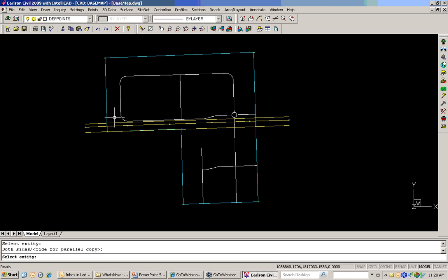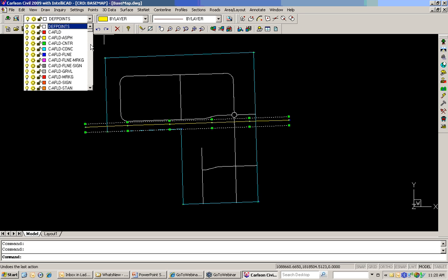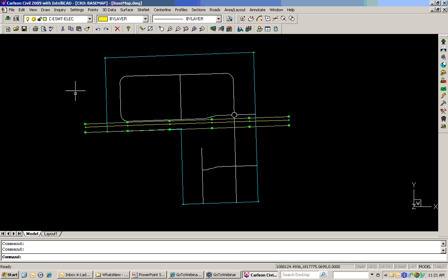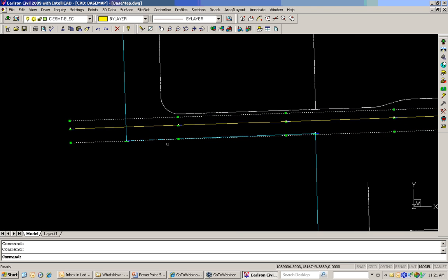The next thing we're going to do is form a closed region, because right now we just have these lines in here. I'm going to change these as layers and set them into the proper layer for my National CAD standards. So I'm going to go into my civil and then easement, and then I'll say this is on my electrical layer, so you can see the colors changing here based on the new layers that these have been assigned to.